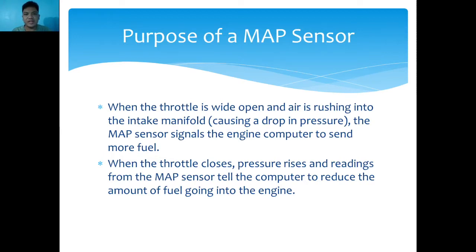So in this part, it's pretty self-explanatory that an intake manifold normally has vacuum at idle, because remember, you have a flap in the throttle body that restricts the air, and only the idle jets are the ones responsible for keeping the engine at idle.